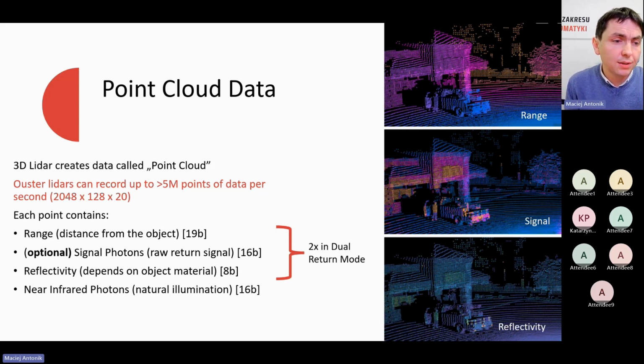So the first 3 signals, this is the information that the LiDAR gets from the laser that it's shooting. The basic principle of how LiDAR works is that it shoots a laser beam, the laser bounces off a certain object and then comes back and is detected. But additionally, the same detector on the sensor that receives photons from the laser beam also gets photons from other sources like sunlight or artificial lighting.